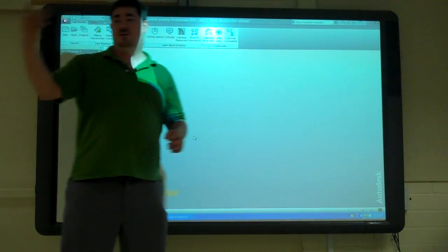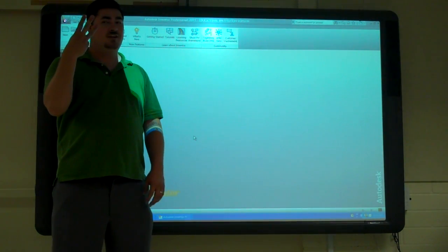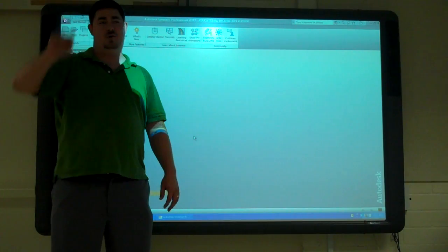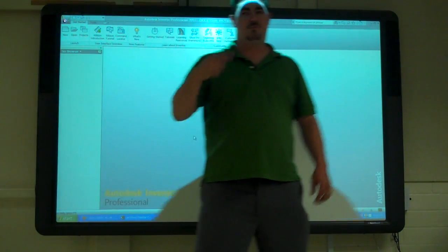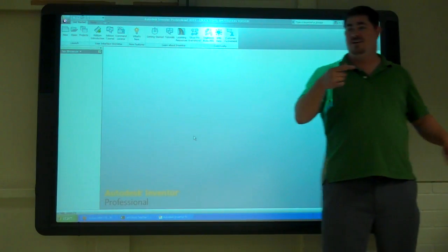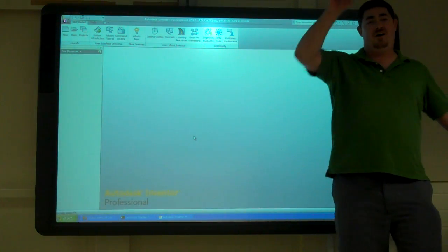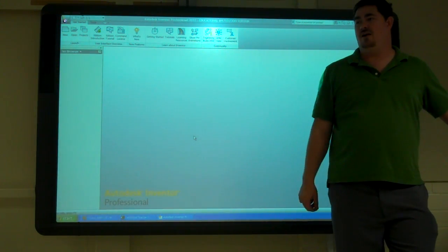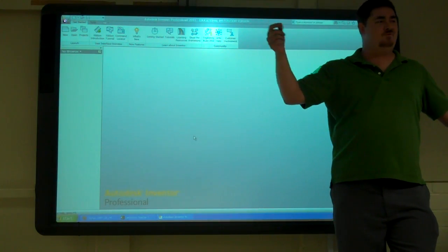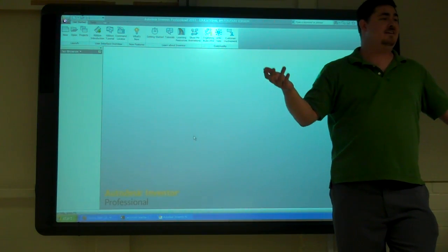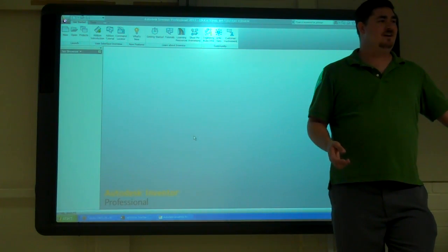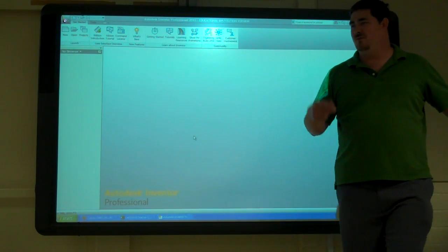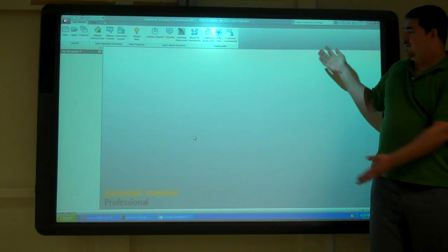And then with that, I'm going to show you how to use the drawings in Inventor. Because then, to do the auxiliary views, it's 3 clicks. You pick the view, you pick the line, you tell it which way to go to make your auxiliary view. And so it'll let you practice some harder things and see what exactly you have to do to get to the right view. Because if you do it wrong, you wasted 5 seconds instead of 20 minutes or an hour or 2. Okay?